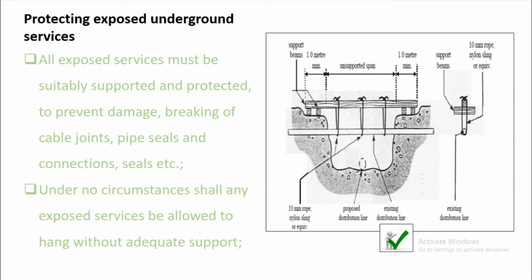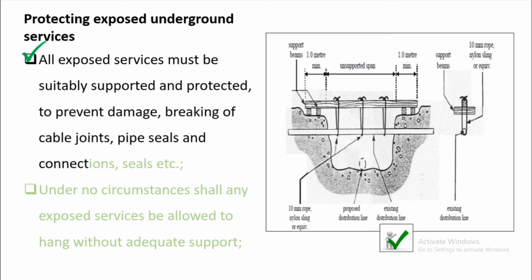Protecting exposed underground services. All exposed services must be suitably supported and protected to prevent damage, breaking of cable joints, pipe seals and connection seals, etc. As you can see in the photographs on the right, your excavation is crossing on the utility.